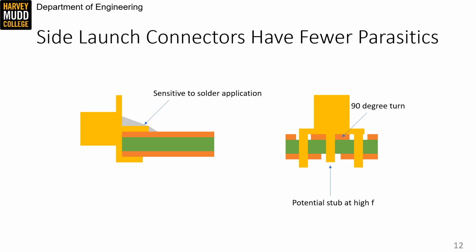Vertical connectors force the signal to turn 90 degrees, which is a bigger deal here than with traces because of the many parasitics that are built into connectors. As a result, side launch connectors are preferred when possible. That said, connector designers know their business, and if you follow the layout recommendations for a vertical connector closely, it'll usually result in a successful connection.